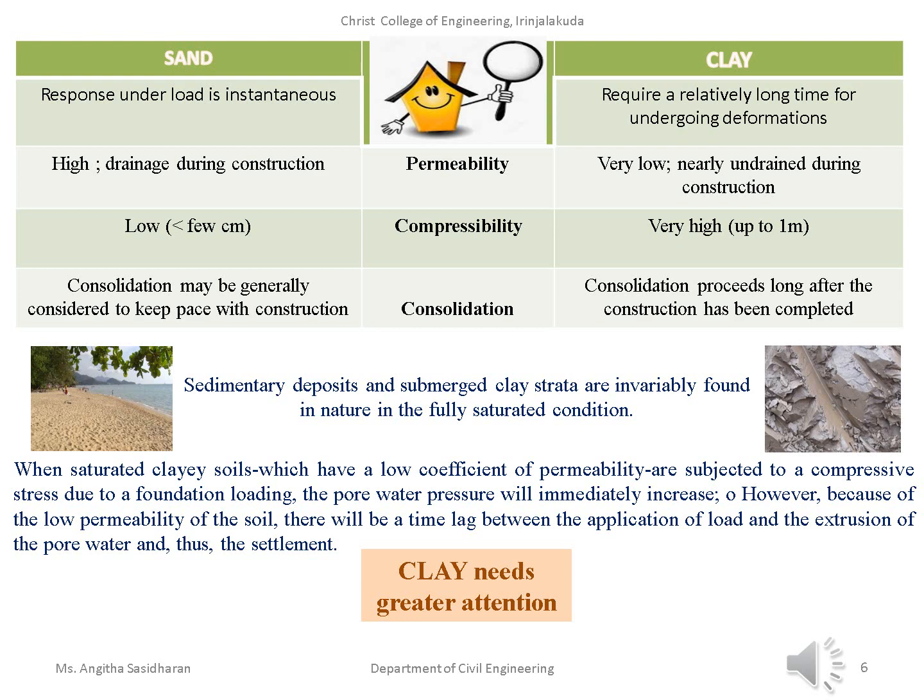And what about clay? The consolidation property of clay. Consolidation proceeds long after the construction has been completed. Even after the construction is done, later the consolidation process goes on. So that is very dangerous, because once the construction is done and the structure is over there, then if consolidation happens, it will affect the structure, causing settlement of the entire structure. So that is very important in the case of clay.